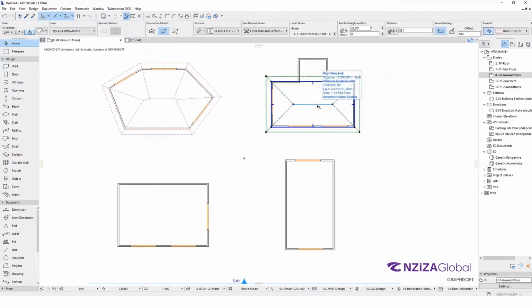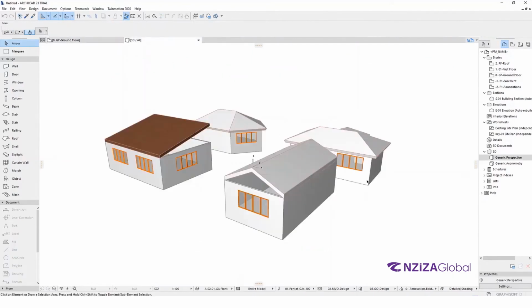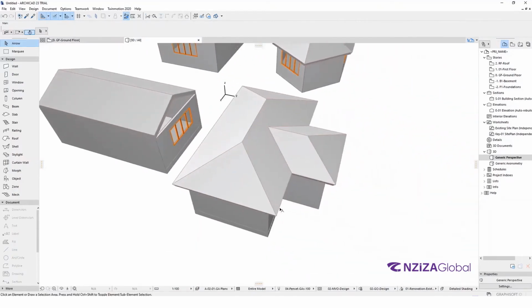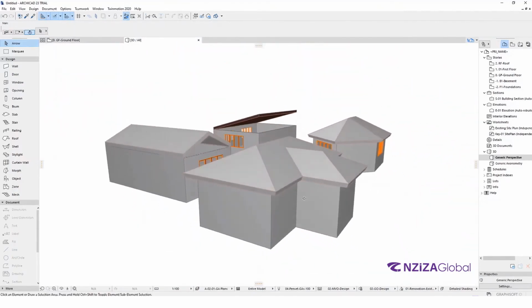After placing your roof, you can still play with the edges and all the details. If you click these black points or blue line, when you click, you will see similar options like walls. You can add new points, insert nodes, or offset edges, or add a new polygon. Click add new polygon, and let's add this part too. It is automatically updated, and we can check on 3D. It is good.